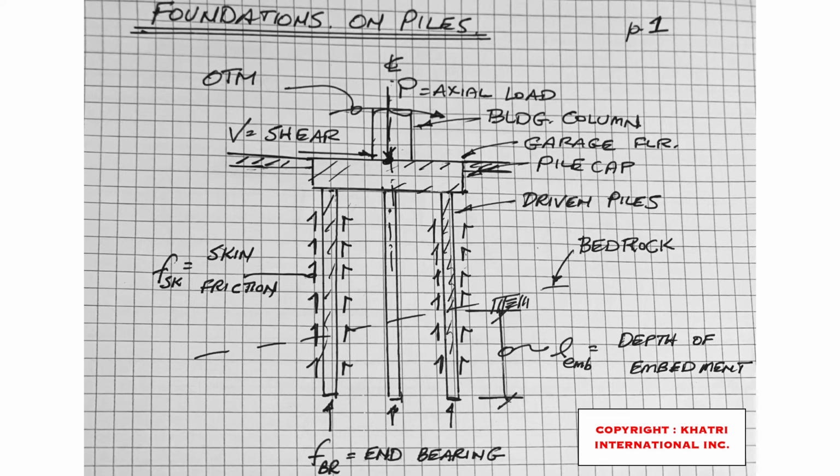I've included this slide, which was in my third report, just as a recap to explain how the pile foundation system works. In the case of Champlain, it was built using skin friction piles, where the friction between the piles and the soil is the governing load path. And if that skin friction slips, then you have problems.